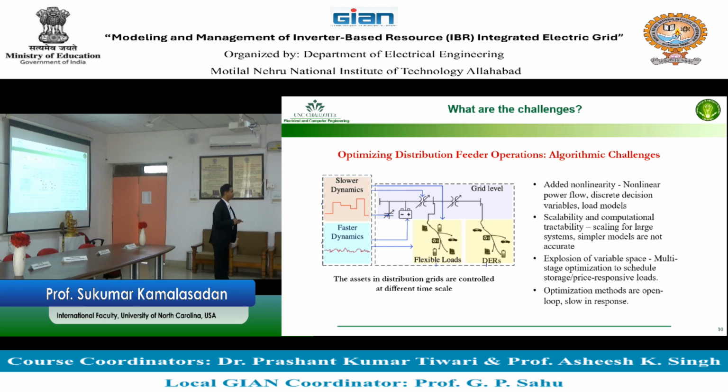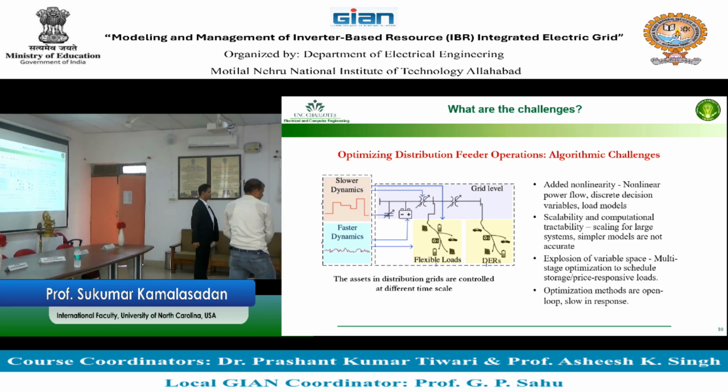Okay, and what does that device do? The devices will be able to generate power based on those set points. So for example, let's assume that you have a PV farm sitting there with a battery. You can send a set point to the PV farm and battery and say, hey, economically or value-wise, you should generate 3.3 megawatt. Then there will be a control system working on that PV farm to generate 3.3 megawatt.